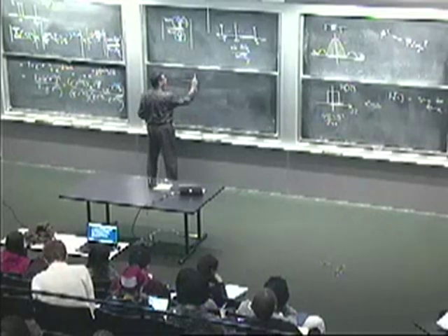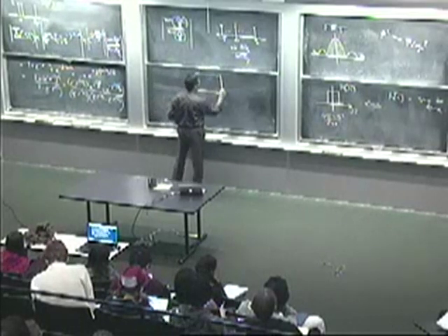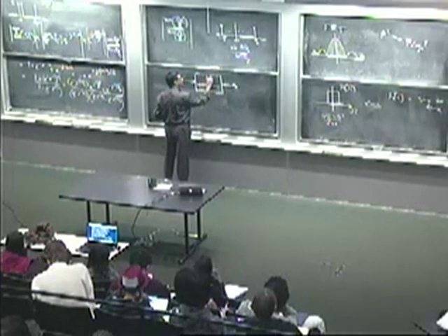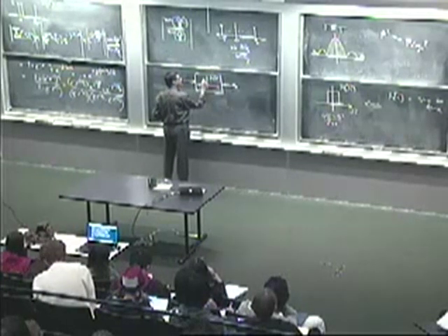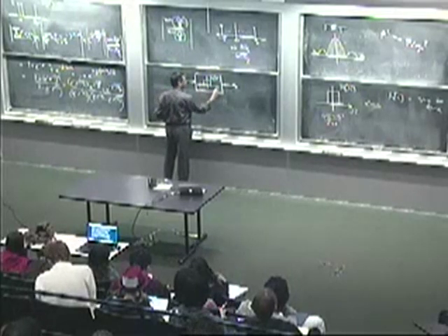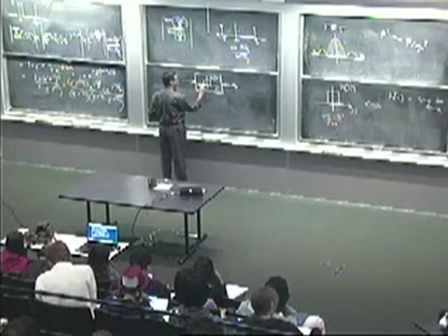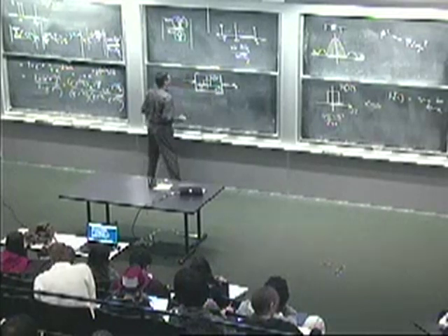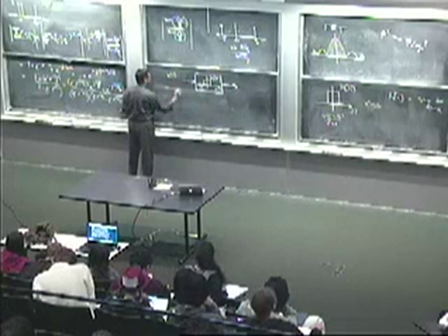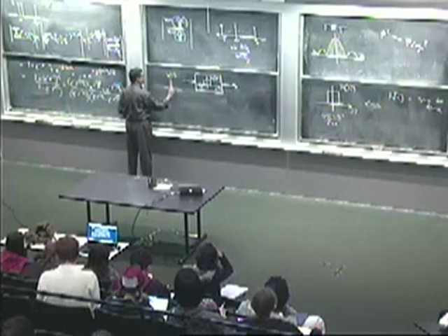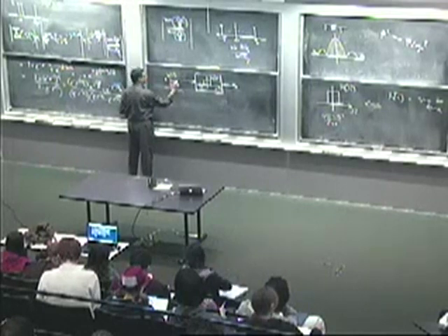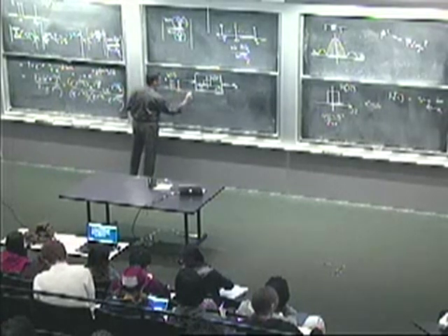So I'm thinking about a channel whose frequency characteristic, this is H of omega, passes low frequencies and then truncates higher frequencies. What I'm going to do is send in an x of n, which is this pulse in time, 256 samples at height 1, and then everything 0.